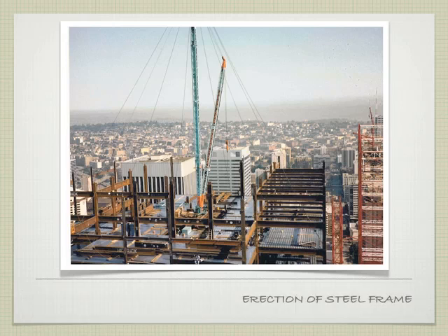So we look up at a bigger building here. Obviously, we're working our way up in floors, but we have a temporary work surface that we're working off of, because we can tell by the cityscape that we're already pretty far up. The other thing about a multi-story building is once you get up a certain level, somebody else can be coming in and doing a concrete topping down below. In this case, it looks like it would be a composite decking instead of a cellular decking, but I'm not entirely sure.